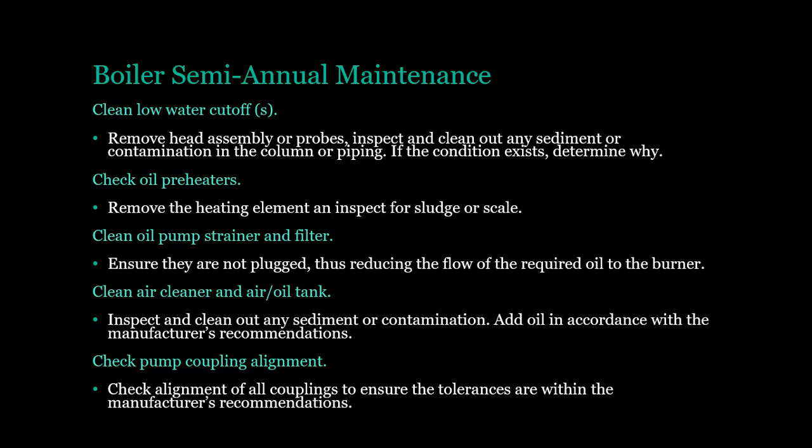Clean oil pump strainer and filter. Ensure they are not plugged, thus reducing the flow of the required oil to the burner. Clean air cleaner and air/oil tank. Inspect and clean out any sediment or contamination. Add oil in accordance with the manufacturer's recommendations. Check pump coupling alignment. Check alignment of all couplings to ensure the tolerances are within the manufacturer's recommendations.